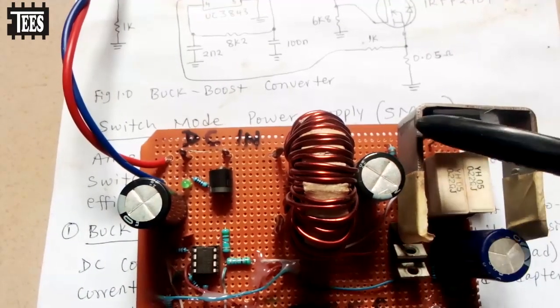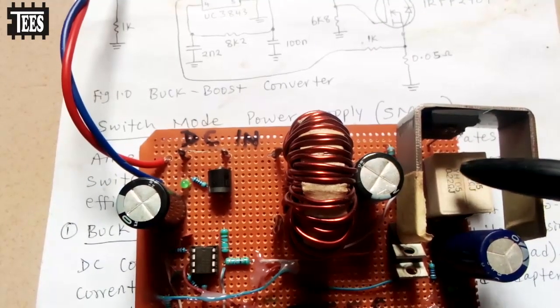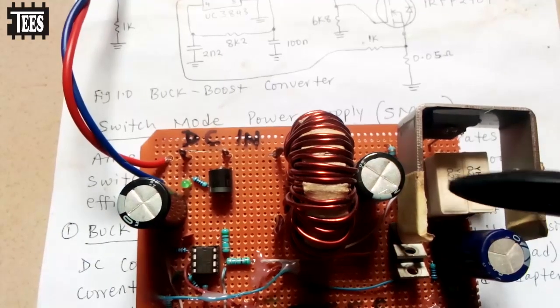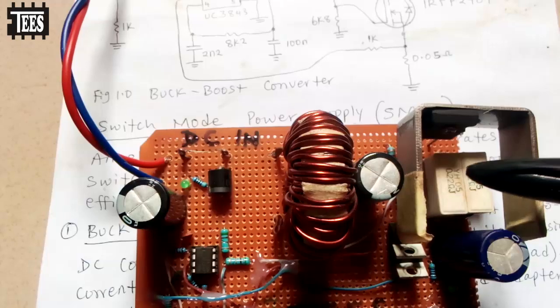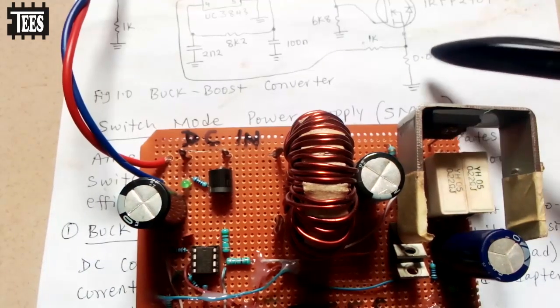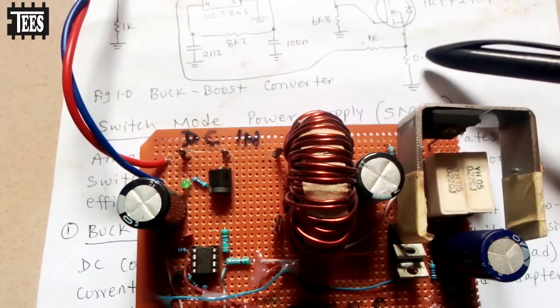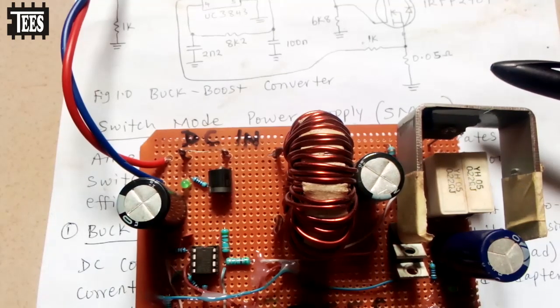So you see, the resistors in parallel that we do in class to pass exams apply to solving a real life problem here. You can see it. And what was the problem here? I don't have this value. I couldn't get access to this value of resistor in the market, so I found out which ones they have, and I had to make a calculation which gave me almost exactly what I needed.